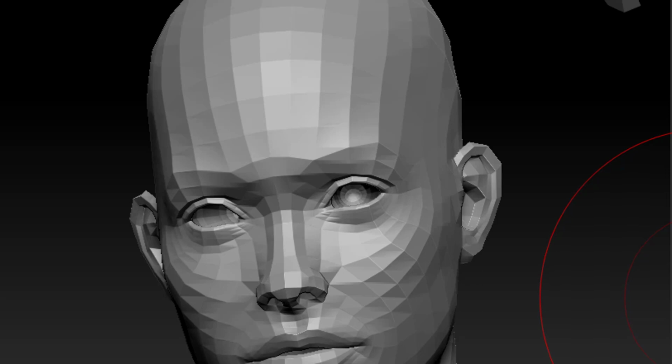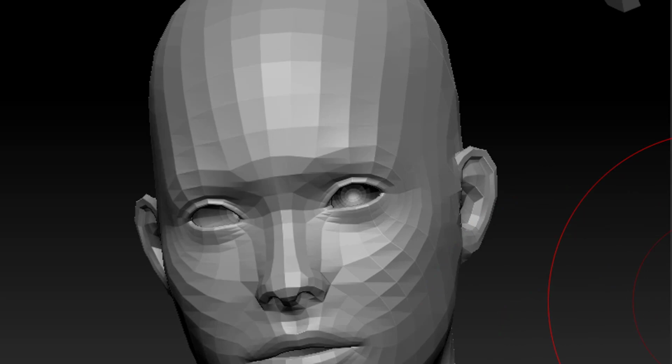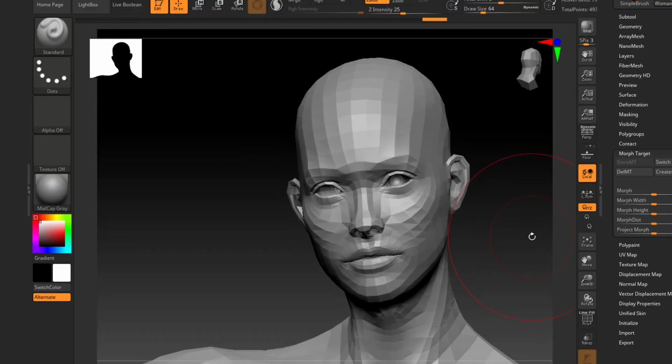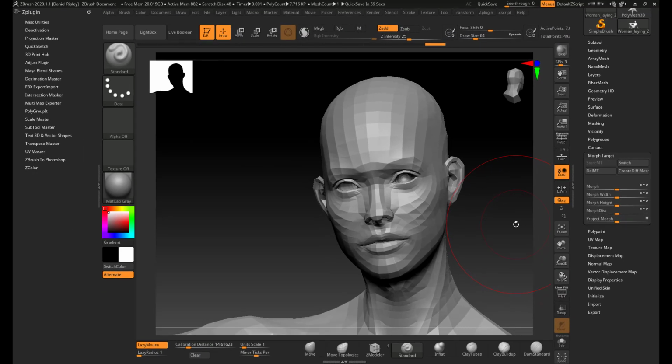If you don't do this task of storing the morph target, when it comes to creating the displacement map, it's going to create a displacement map based upon that mesh, not this one. And this is really important because when you bring your maps into your external 3D application, it needs to be applied to exactly the same mesh the way it was between there and in Zbrush.